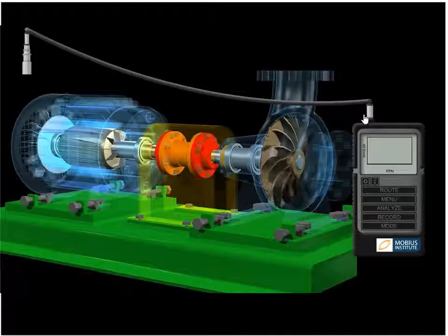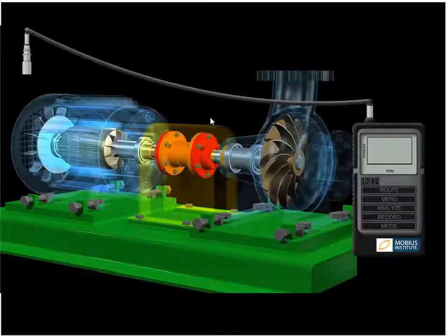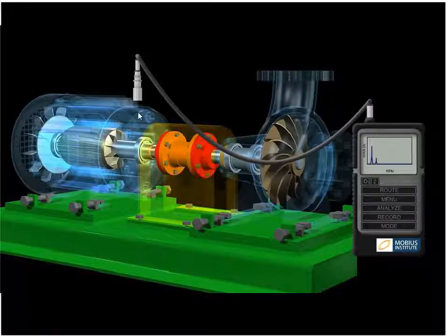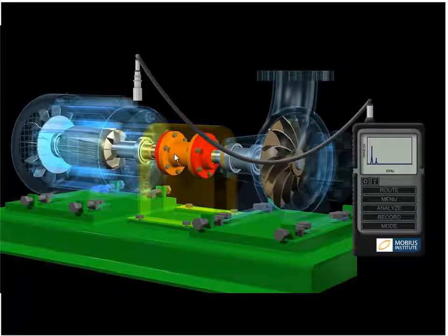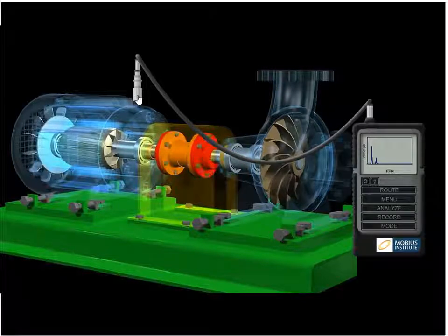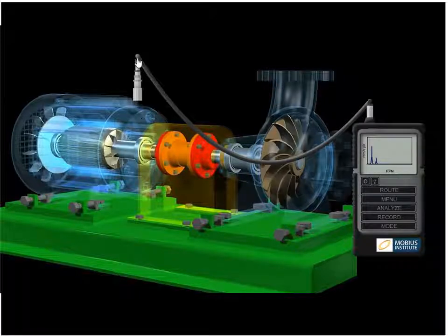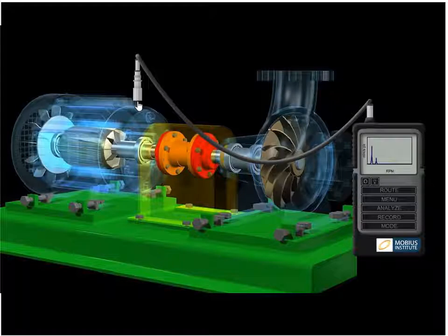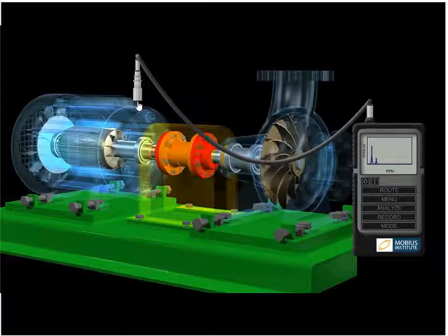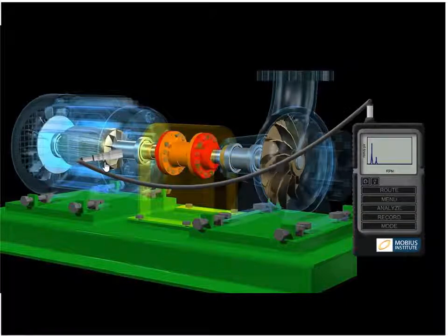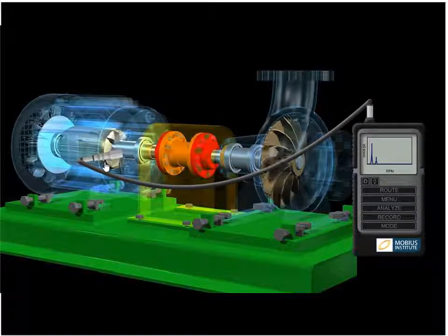Okay, so the way we do this is, as you've just seen, we can put the vibration sensor up there on the bearing, and all the vibration is transmitted through the machine itself up to that point. The sensor has to be mounted properly. That is very important, so that all those high and low frequencies get up into that sensor. But the fact is, when we mount it up on top, that is sensitive to the vertical motion. Whereas if I move it to the horizontal location, that's now much more sensitive to the horizontal motion.